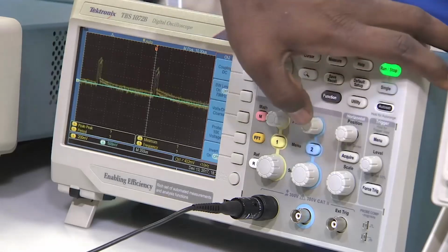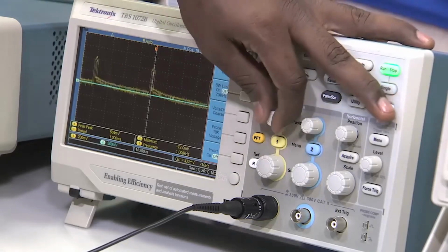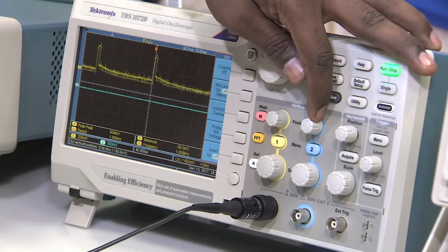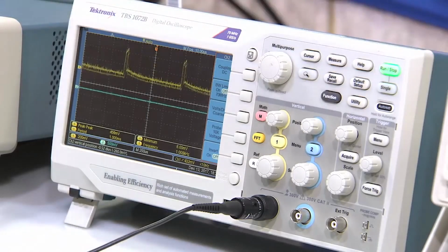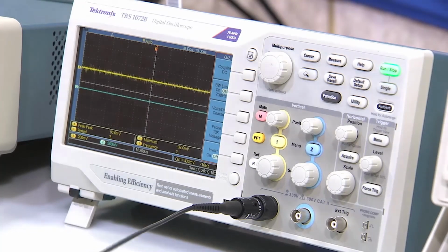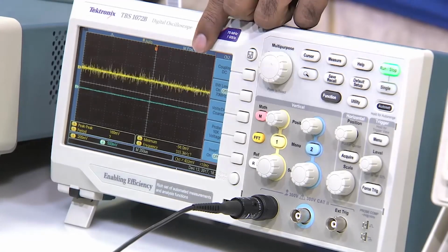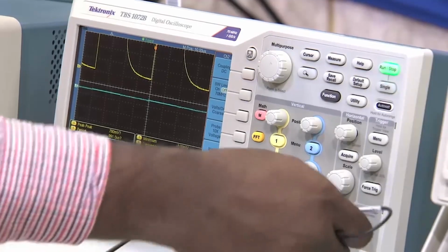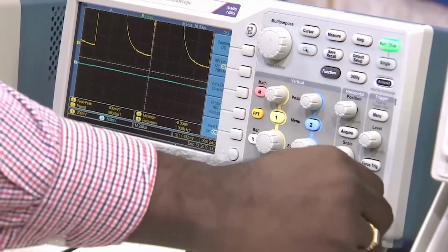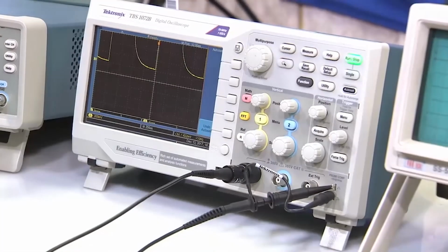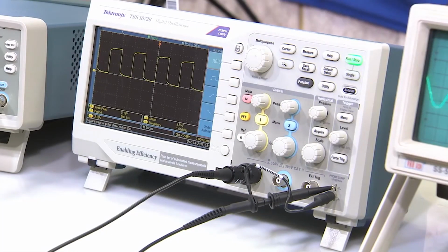Right now channel 2 has no signal, so probably we cannot see it. But to first understand the oscilloscope, you should connect the oscilloscope for the probe compensation. When you start using the oscilloscope, first thing that you have to do is compensate the probe. That means, when you connect the probe to the oscilloscope, you will connect it to the probe compensation knob. It is right here, you can see he has connected to the probe compensation knob, the other one to the ground, and then he is doing the auto set.